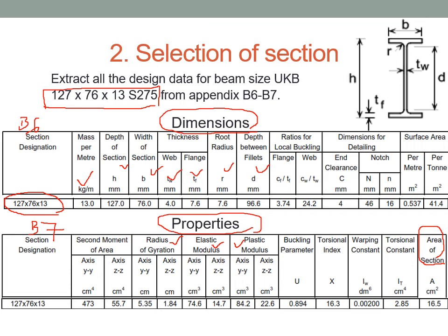Please take note on the unit here. At the dimension part, all the units are in millimeter. However, at the properties part, they are using centimeter. So you need to make sure when you are using any formulas that the units you use are similar.